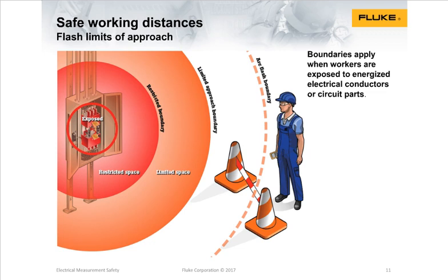What you find after running some of the calculations, depending on whether it's a dual-fed panel, depending upon the total current coming into that panel, is that you might come into virtually an auditorium and find that with an open exposed panel, anyone entering that area needs to wear arc clothing. You may find that that is a larger area than what you had first thought of. I once had an electrician tell me it's very similar to standing before a loaded cannon when you're working on these panels. So I urge you definitely wear the correct PPE and follow the safe procedures.